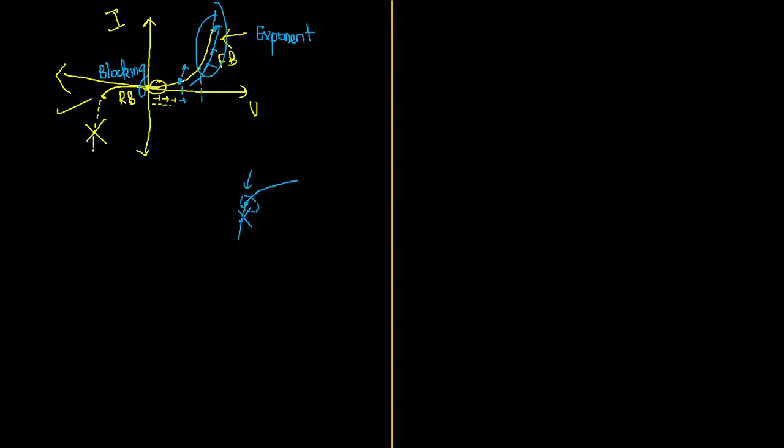Diode will be blocking. So in reverse bias, there is no current flow, so the value of current is 0. There is no conduction. In reverse bias, the current value is very small, in microamperes or nanoamperes, so almost equal to 0. Microampere means, suppose I write the current value as 1 into 10 power minus 6. How will you write this current?